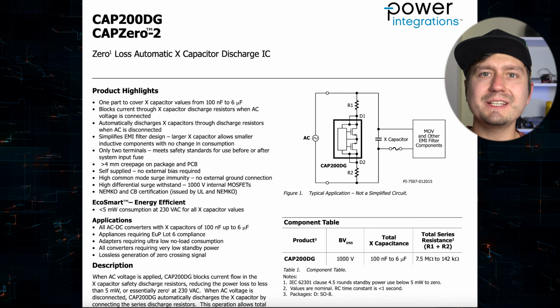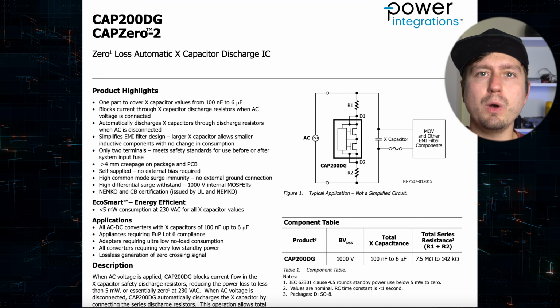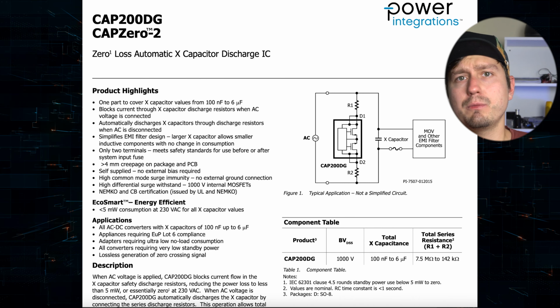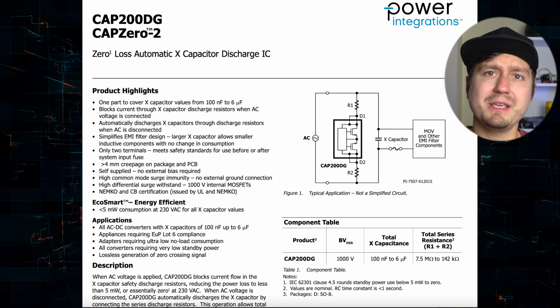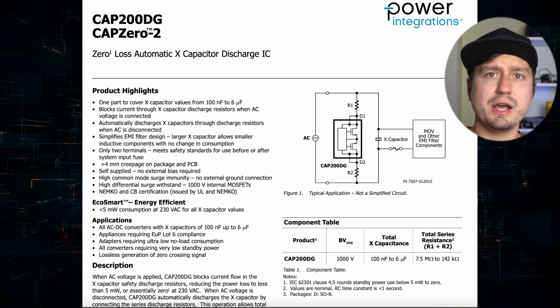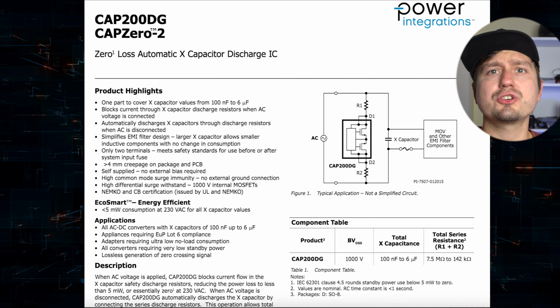The only thing that I haven't talked about on this circuit is a capacitor discharge IC, and what it does is discharge capacitors, both X and Y, so that when you touch mains by accident, for example immediately after unplugging the IEC connector, you're not going to get any kind of shock or uneasy feeling, which you would get if you didn't have this IC. So this is basically the only purpose that it has.